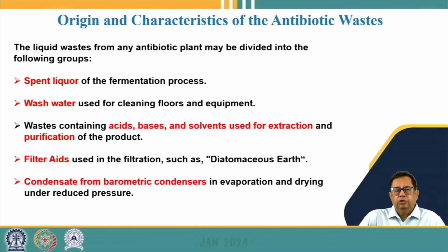it can also be disposed of using safe methods of disposal. During the production of antibiotics, a lot of wastewater can be generated. This liquid waste can be divided into the following groups. We can have the spent liquor generated from the fermentation process. We can have the wash waters generated from cleaning the floors, the equipment, the steaming process, etc. The waste may contain a lot of acids, bases and solvents which we use during extraction and purification, so this may also find its way into the wastewater.